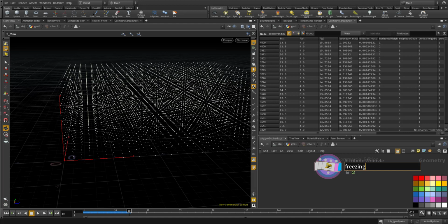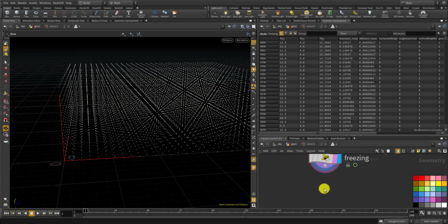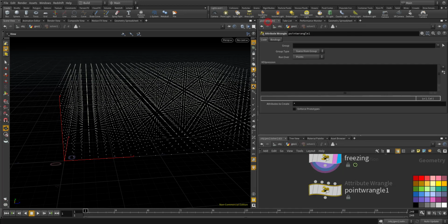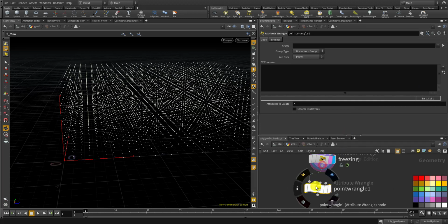Okay, now the next step is attachment, where you convert a boundary cell to a snowflake cell based on the boundary mass. If the boundary mass is big enough, then convert the boundary cell to a snowflake. So another point wrangle. Yeah, this tutorial is really VEX intensive. You really need to know how this VEX works. But it's kind of fun once you know it, I think.